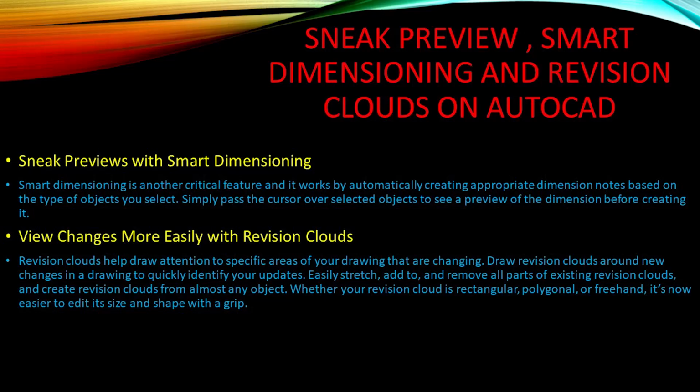But if you are just sending it to a client or just for educational purposes, you can easily save as PDF to save space. Then whenever you want to work on the drawing again, you can easily copy it back to the drawing. So now, furthermore, we have your sneak preview, smart dimensioning, and revision cloud on AutoCAD. Smart dimensioning is another critical feature, and it works by automatically creating appropriate dimension notes based on the type of object you select. Simply pass the cursor over selected objects to see a preview of the dimension before creating it.